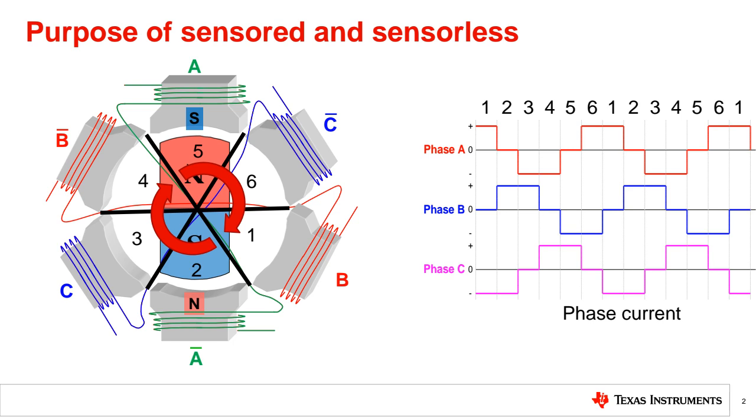For example, we have absolute encoder. Absolute encoder means that it detects position with high accuracy. However, on the other side we have incremental encoder. So we can divide the encoders into incremental and absolute. Okay, absolute means that it detects the position of the motor absolutely. However, incremental encoder detects the position at 1 over, for example, 2500. It's very sensitive, but it's not sharp.